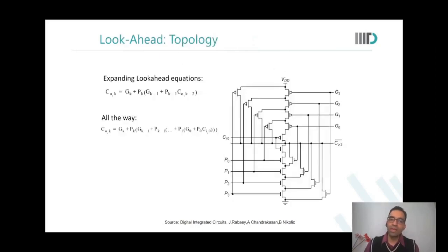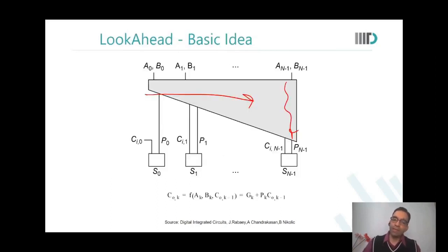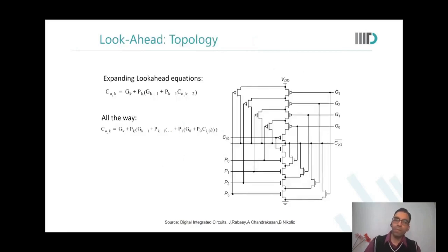So what is the idea behind it? You say that, okay, to be able to anticipate the output over here, I don't need to wait for ripples or even inputs to come from this side. Let me, at every gate itself, use the earlier gates iteratively.